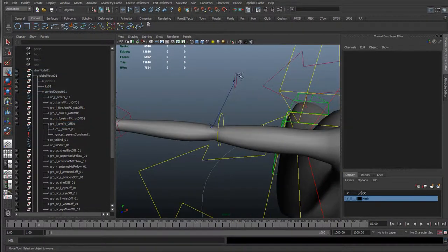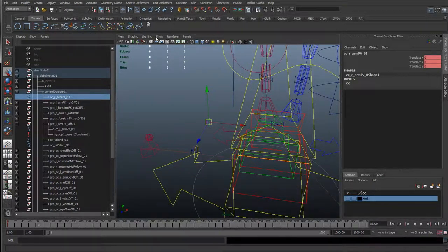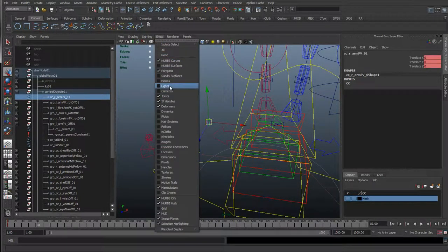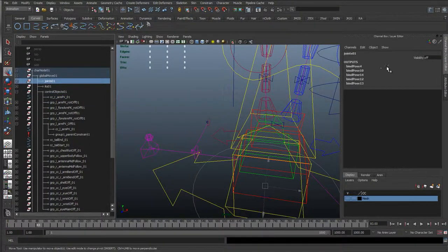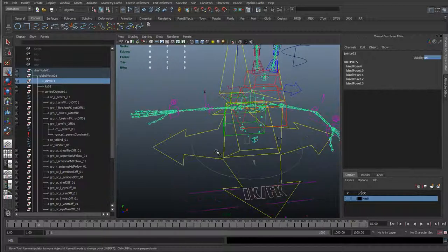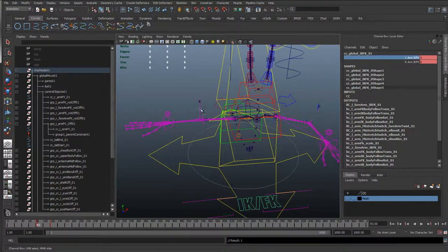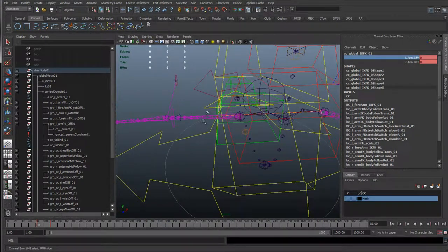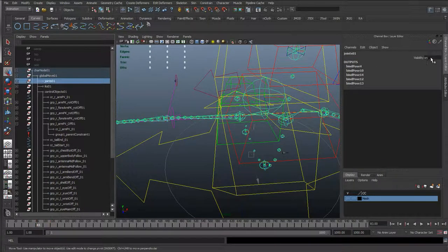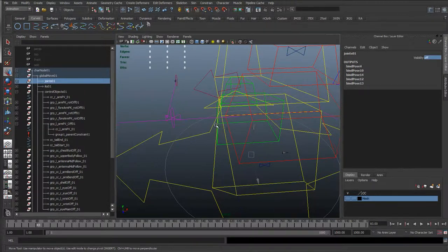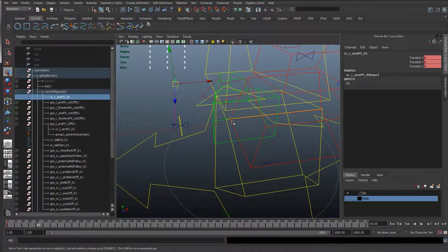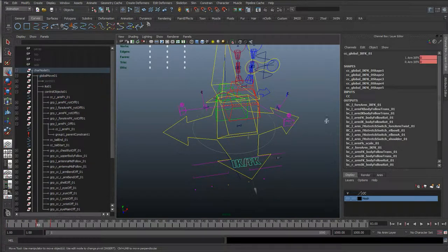So over here we need to do the same. So I'm going to hide the mesh. I'm going to show joints. So joints are shown, so I need to display the group. So what I'm actually going to do here is switch to, and if you've got a case like this where you can't see the control to snap it to, so actually I'm going to hide the joint. So you could snap it to the joint here because we remember the pivot was the same as the joint. But just for instance, if the pivot wasn't the same, I want to snap this to a control that I can't see. What we just want to do is go to FK,